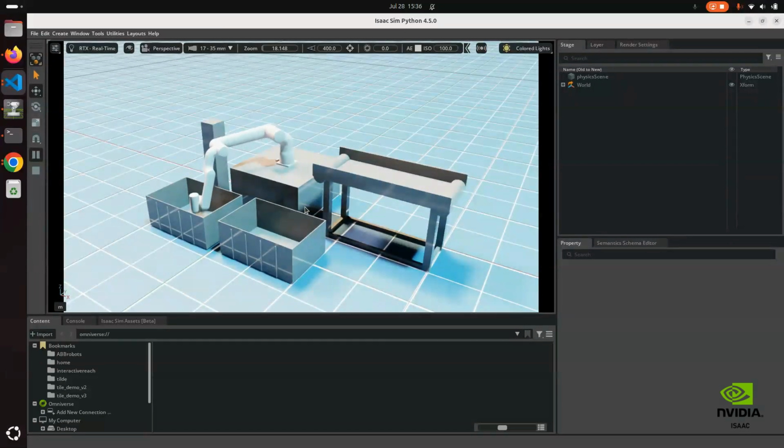Often you'll have inputs and outputs, you'll have various places that your robot needs to reach in certain ways, and that will all put constraints on how your cell can be designed. You can't just rock up and be like, oh, we'll have some boxes over there, we'll have some conveyor belt over there. There's always going to be some iteration on this, and you might have space constraints. You might want to have a lot of these cells tiled effectively. You've got floor space constraints. There'll be other machines that they have to be near that they can't run into, that sort of thing.